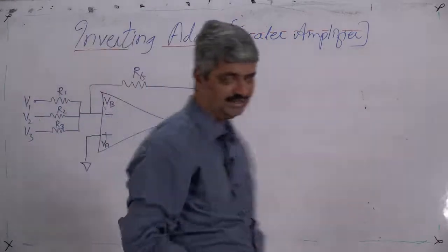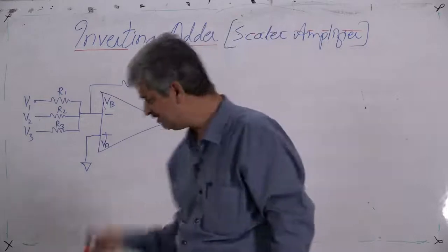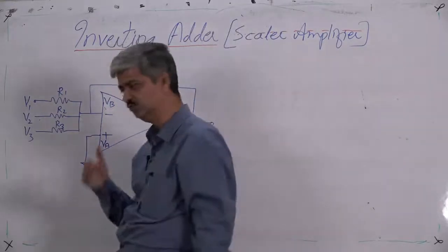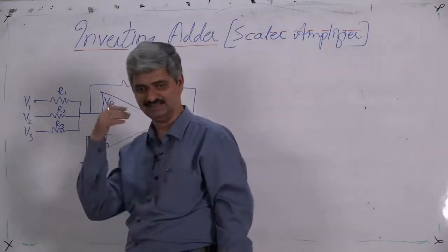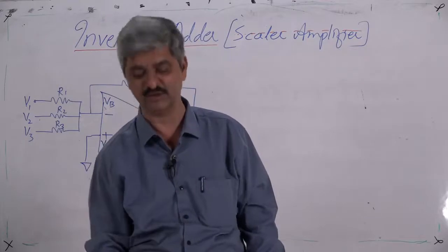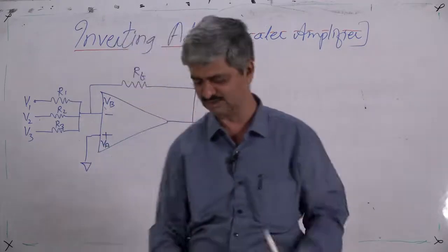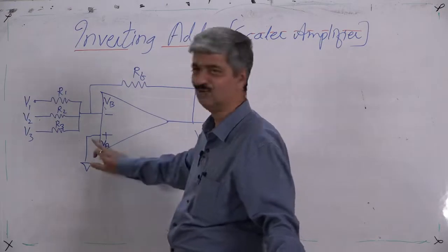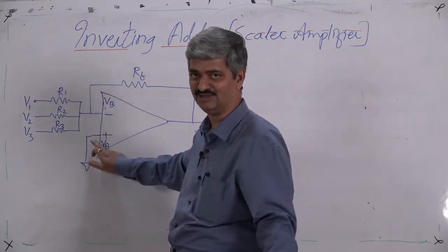Now calculate the output. This is most simple because, first, I think now there is no need to say about the first step, that is disconnection of the op amp, it is logical, just like a question whether you have taken your food. So do not ask every time. So we go from the second step. Calculate the non-inverting voltage. Here there is no need of calculating, it is directly grounded.